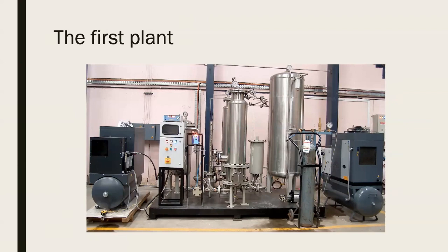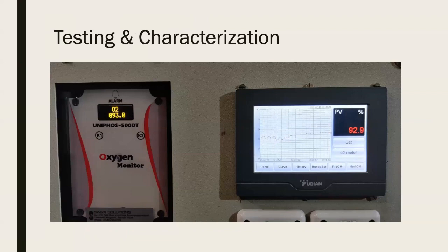This facility is still there in our lab. We did a lot of testing on the facility also. So you can see we are getting 93+% oxygen. This is on a calibration system. This is on the practical system that we implemented. Typically, most of the sensors that we have are all available in low concentration range. Now, what we wanted was a medical oxygen generator in the high concentration range. So we had to struggle a little bit to actually discuss with the supplier to recalibrate their sensors. So it was an interesting journey there.